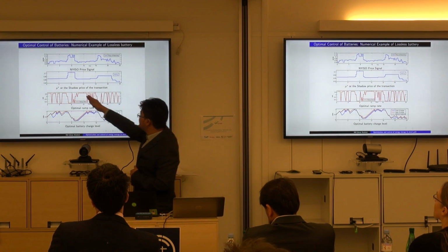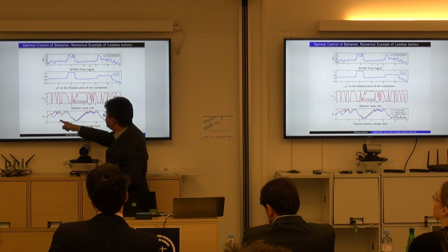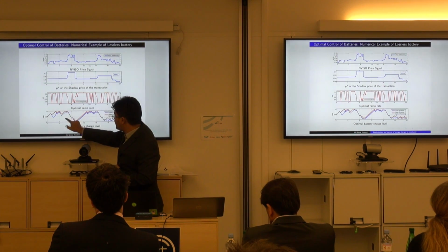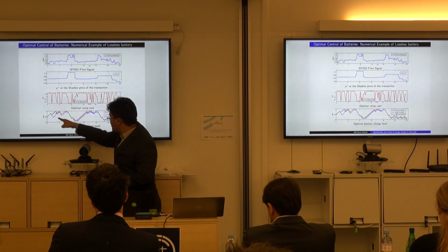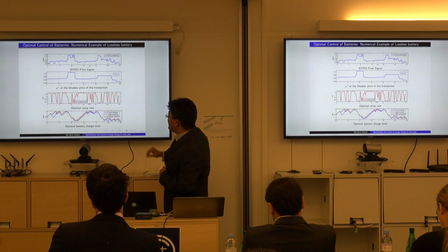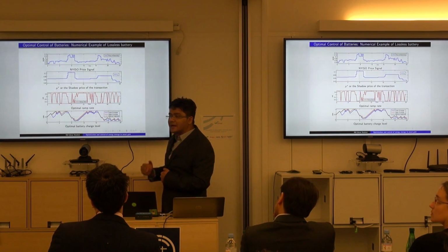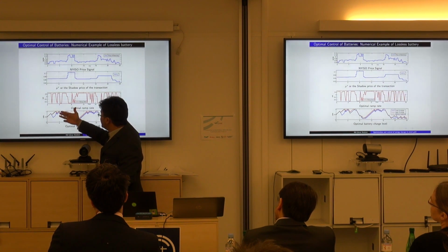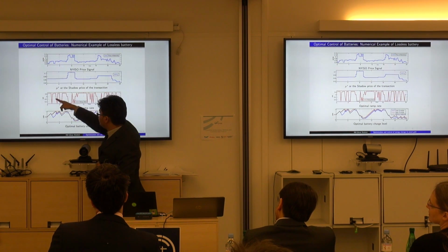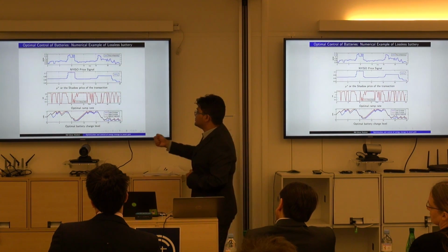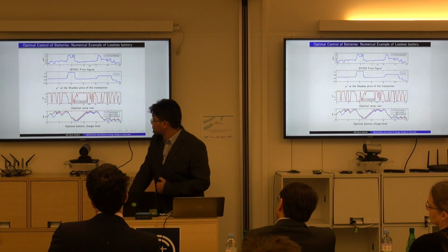It changes whenever the battery capacity reaches B min or B max. Here I'm showing both the envelopes, the lower and upper, and the optimal battery capacity shown in the black line in between. This plot shows the ramp rate, charging and discharging. For example, since the battery is lossless, even for this small peak there is a charge and discharge cycle going on, which would not occur if there were charging and discharging losses.